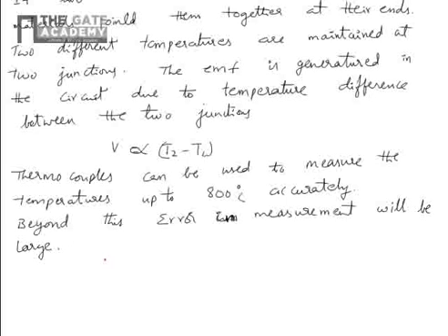During machining of normal materials the temperature will be above 500, whereas during machining of titanium alloys the temperature goes above 800. Such temperatures can be measured by a pyrometer, an optical pyrometer, or a disappearing filament type of pyrometer.